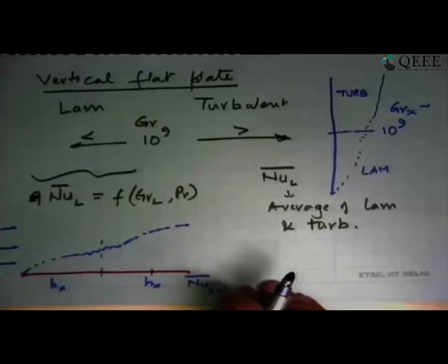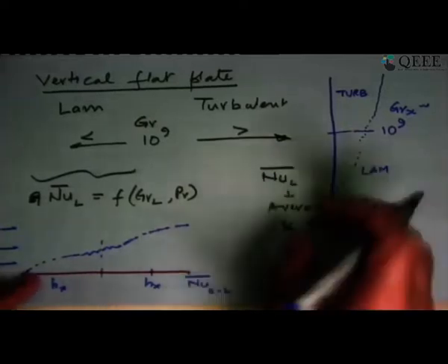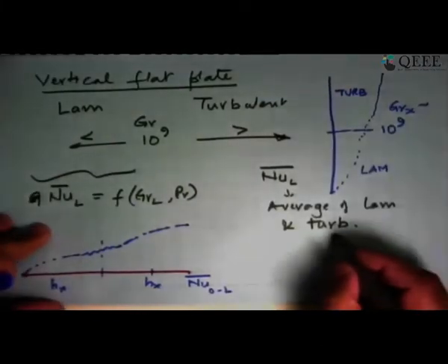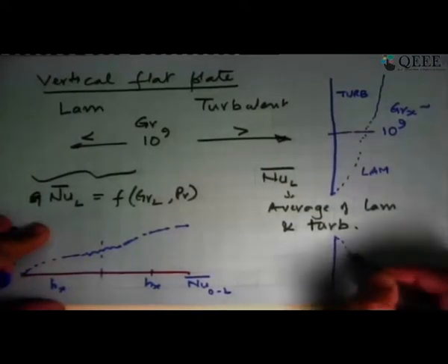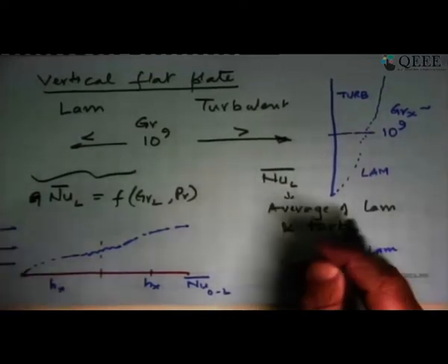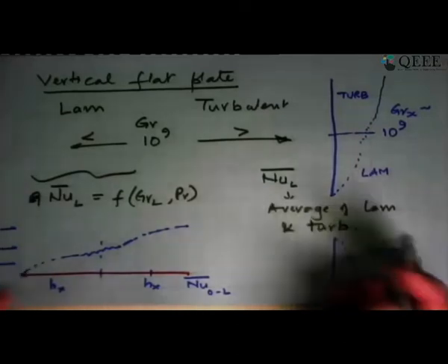So in the problem, if the Grashof number is less than 10 to the power 9, what we conclude is that the natural convection boundary layer that builds up on this plate, or in the opposite case where the plate is cold and the boundary layer builds like that, is a laminar boundary layer, and you have to then pick up that particular correlation for this.